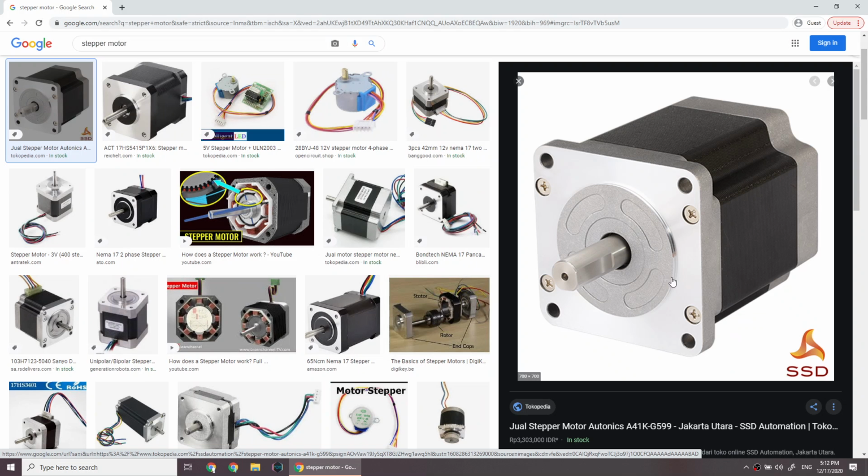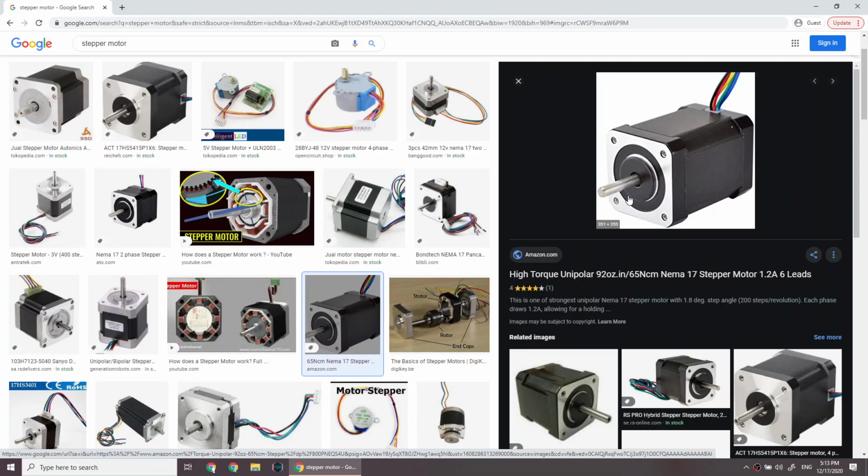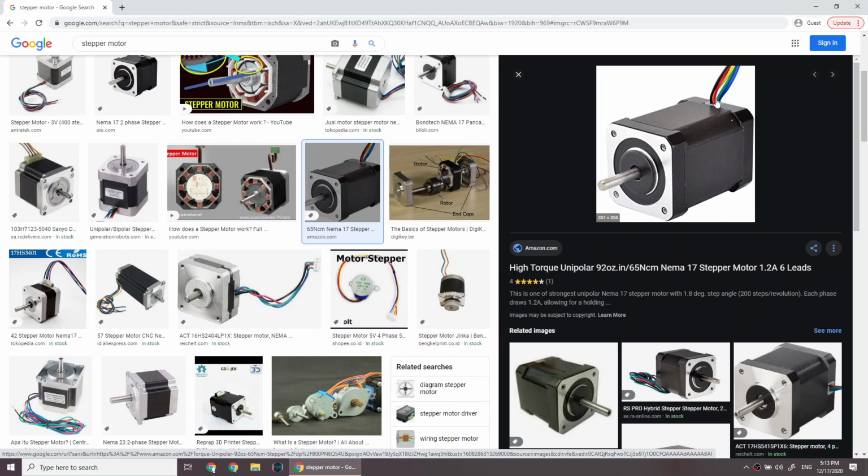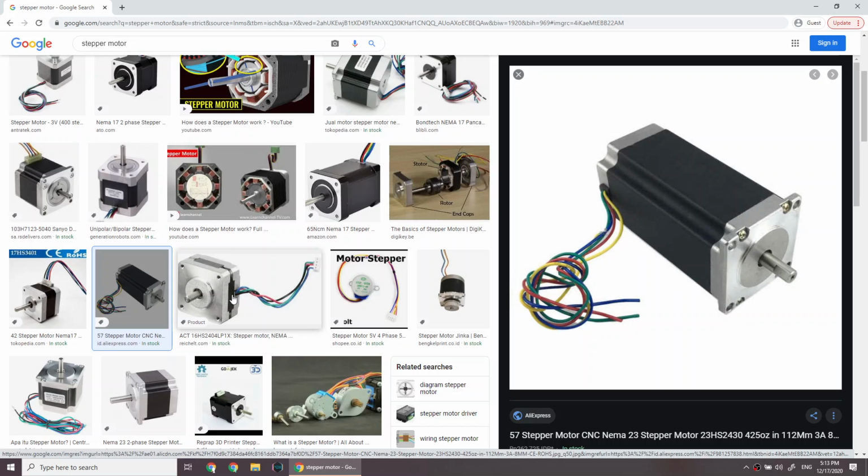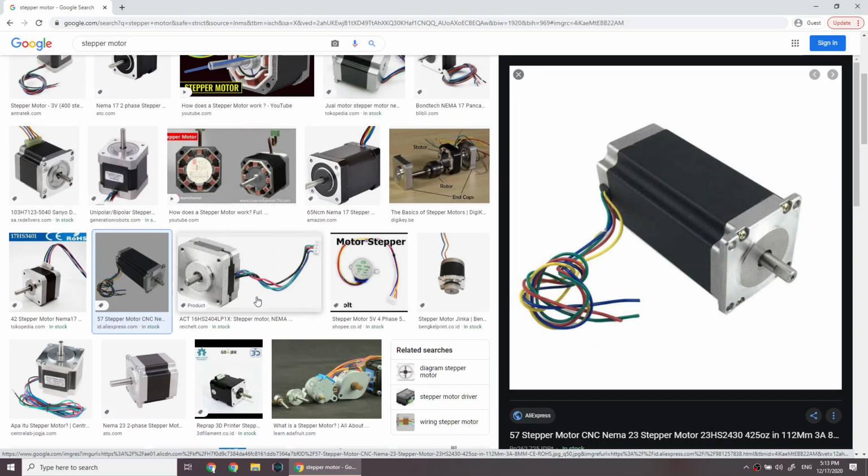Usually stepper motors look like that. It looks like a box. It has an axis like that, and it has several inputs. It is not like a usual motor that has just two wires that you connect to the power source and it rotates. It is different. Usually it has 4, 6, or maybe more inputs. But the trick is, you cannot control this motor directly.